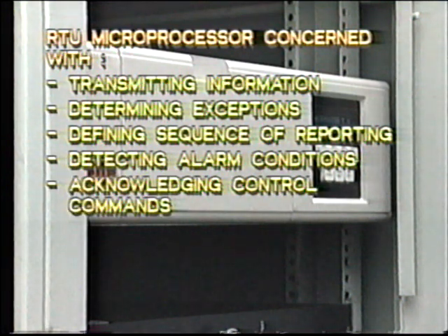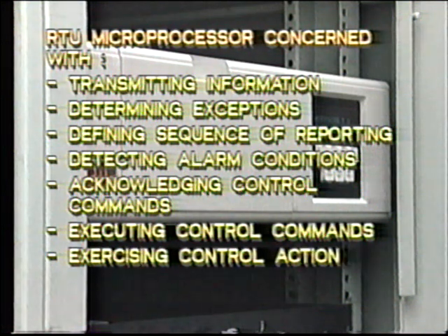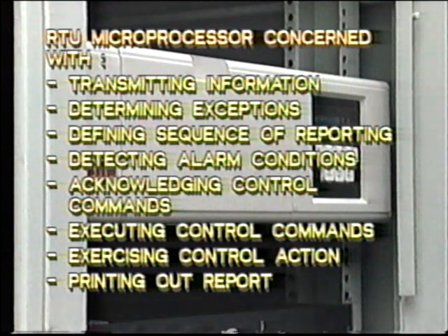acknowledging control commands from the master computer, executing control commands from the master computer, in some installations exercising control action, such as load shedding, directly as a result of measured conditions referenced to internal programming. In some installations, printing out a sequence of events report.